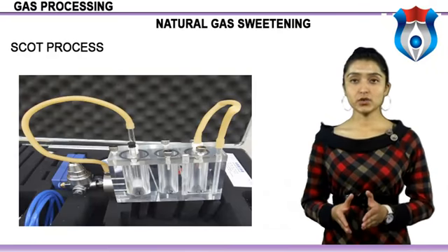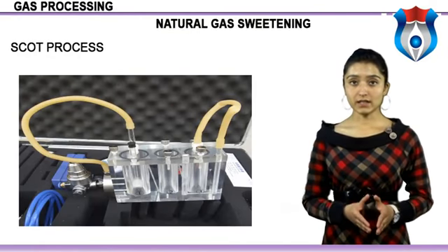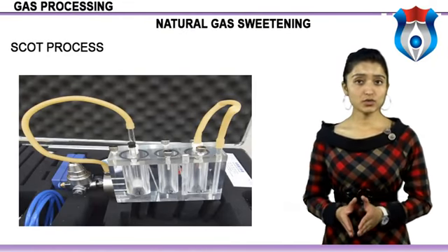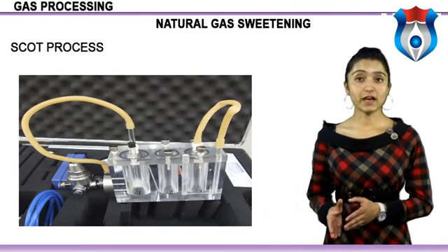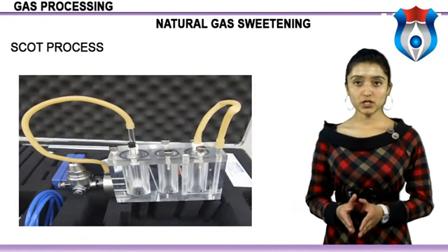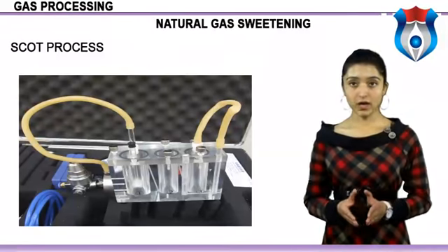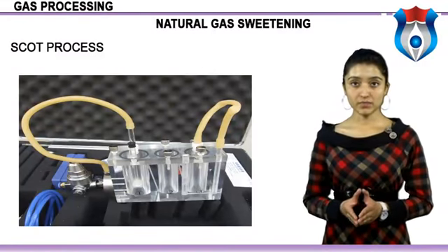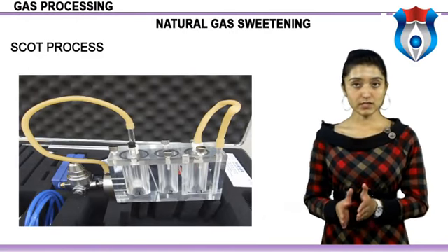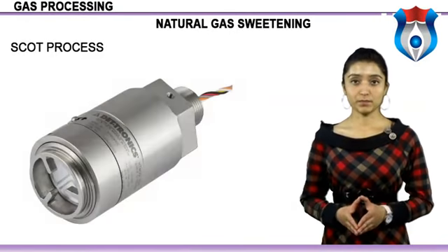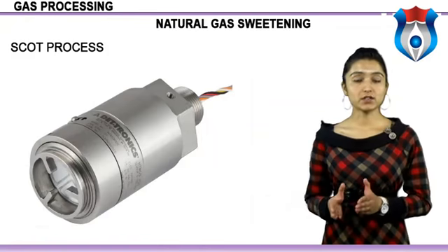The entire COS, CS2 and SO2 in the closed unit gas are converted to H2S by the following reaction: COS, CS2 and SO2 plus H2 gives H2S plus CO2 plus H2O. These reactions are highly exothermic.